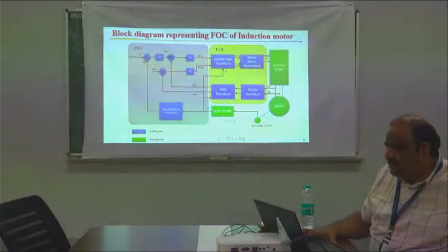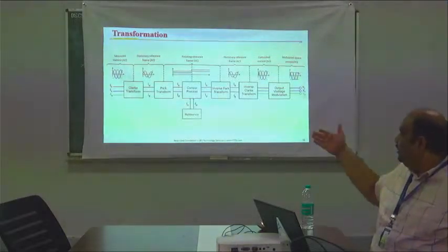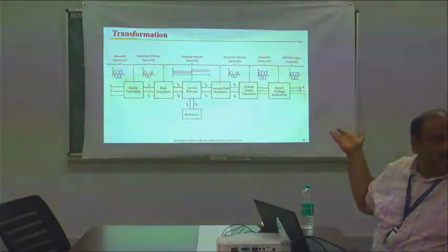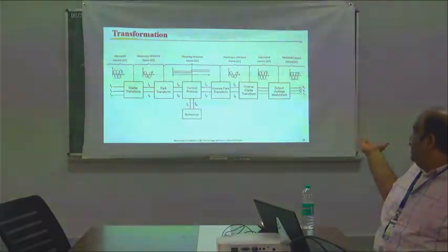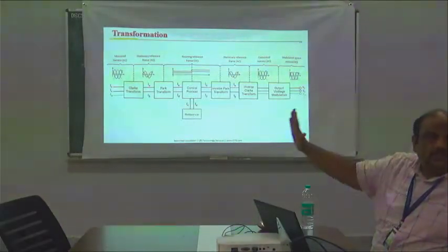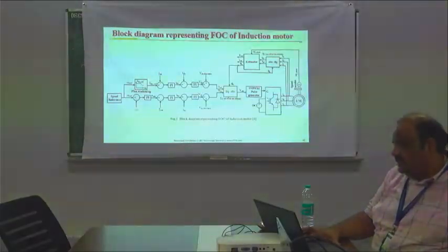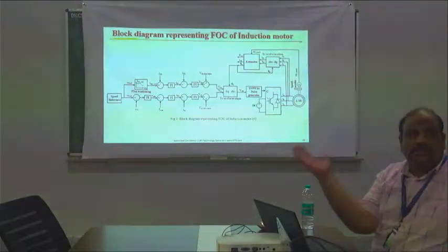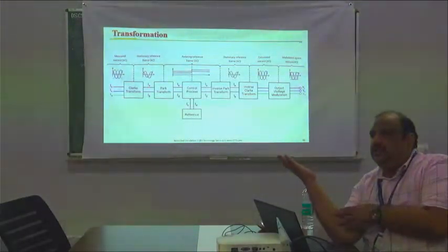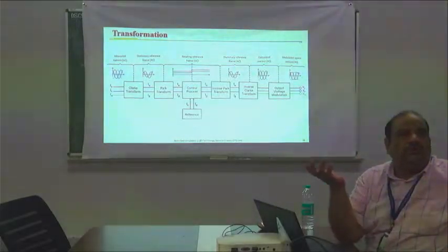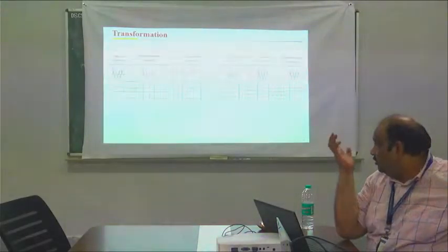That is how this same block diagram works. So how this transformation goes with an equation: sinusoidal to DQ, then aligning yourself, it goes to the DC component. Again from there it goes to the machine as DQ, then AC, and then to the space vector. So this is how the transformations also go. All this I showed in the previous part. So each and every one is aligning yourself to the rotating reference frame, which is the DC component. You are aligning your quantities with the rotating reference frame. So how do you align? AI doesn't know anything. You need to make that alignment.